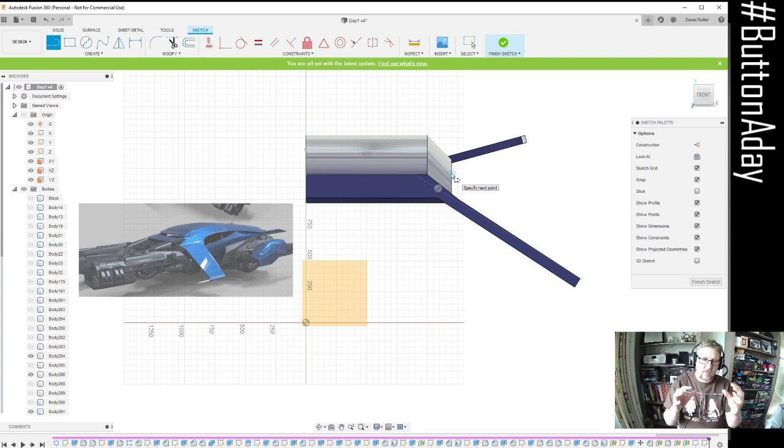If you go from a sketch with very few to a sketch with very many points, it's trying to create weird faces that blend those together. So even if you end up adding additional points into a straight line, so instead of just doing one straight line, you maybe do 3, so you end up with some points in between, that's a good way of getting around things.